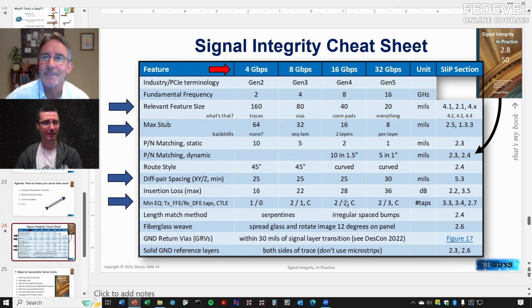This is interesting because some people may think, oh, I routed PCI Express Generation 5, everything is working perfectly, but it doesn't mean it's really working at the top speed. I think that's the takeaway. A serial link will look like it's working, like there's a connection, there's communication, but is it optimal? Is it working as well as it can be working? This is the world of signal integrity, really. Let's get margin. Let's make it work as well as it possibly can work. But that was a great question.